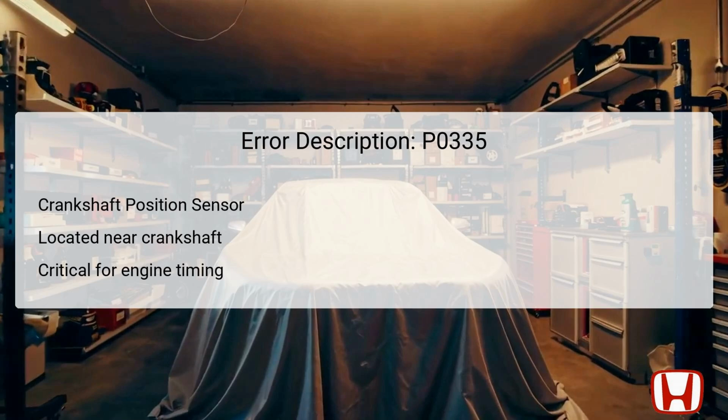A faulty CKP sensor or issues with its wiring can send incorrect signals or no signal at all, resulting in DTC P0335. Properly functioning sensors ensure the engine runs smoothly, while a malfunction can lead to several concerns, such as stalling, hard starting, or poor acceleration. Now that we have a grip on what the error entails, let's look at the potential causes behind this DTC